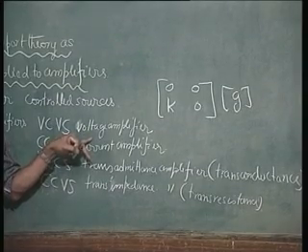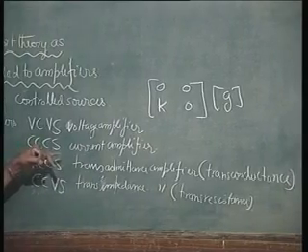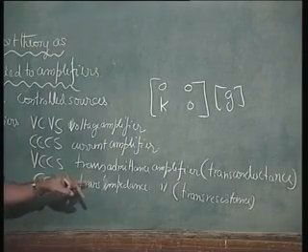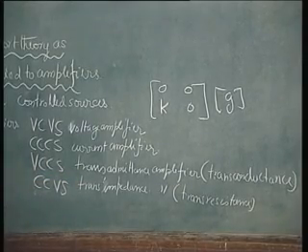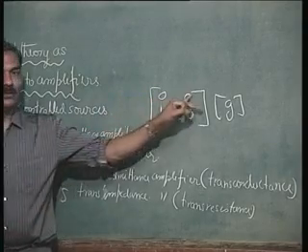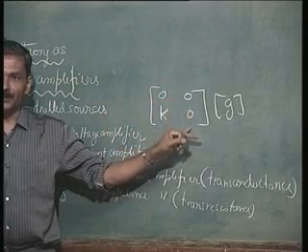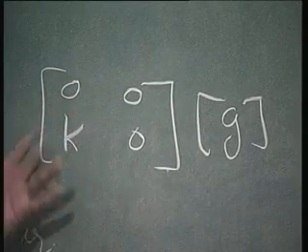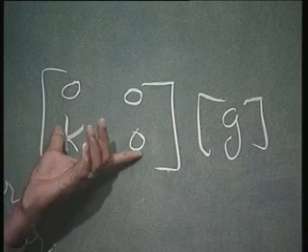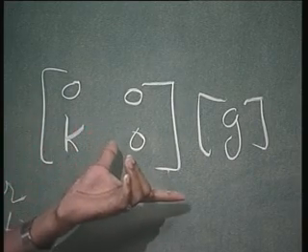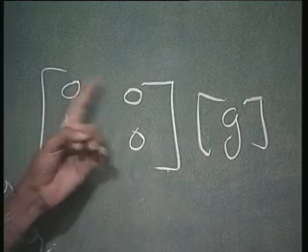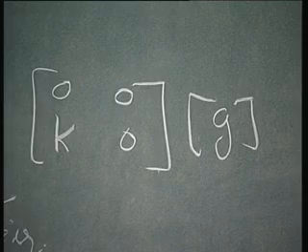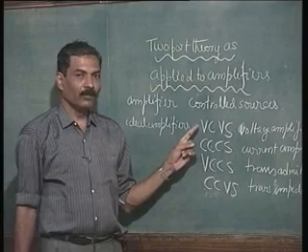What it simply means is, if I try to represent a current amplifier or a transadmittance amplifier or a transimpedance amplifier in terms of G parameters, any one of these three will go towards infinity. So for an ideal amplifier, these things will become meaningless. Only in the G matrix can this be meaningfully represented, and these parameters should go to 0, and this is the only transfer. So that defines a voltage controlled voltage source.